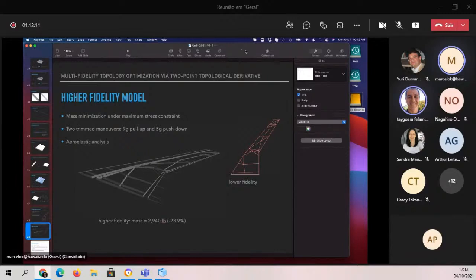So then what I do is I do a barycentric first and test the quality of the mesh. I use two parameters: aspect ratio, and angle, minimum and maximum angle. If the quality of the mesh is acceptable, I continue with the barycentric one that I did. If the quality of the mesh is not acceptable, then I remesh. But if you remesh, you have to be careful in my case.